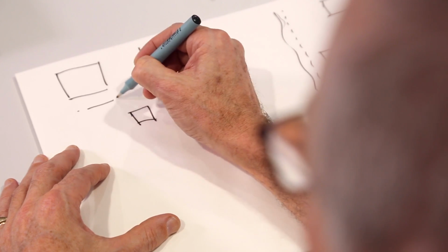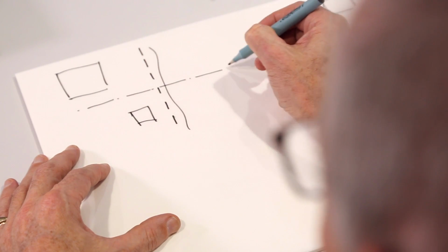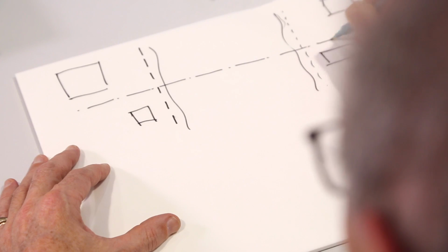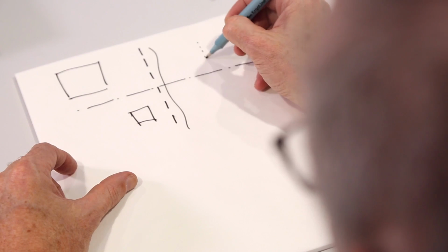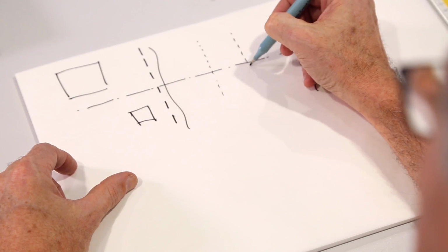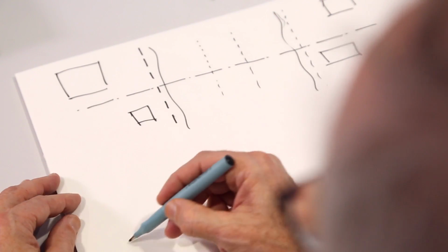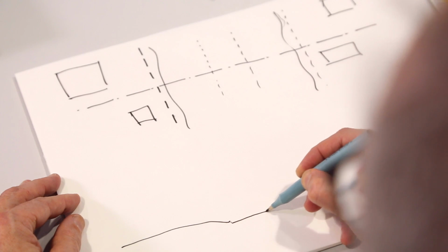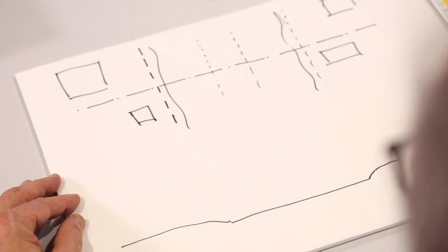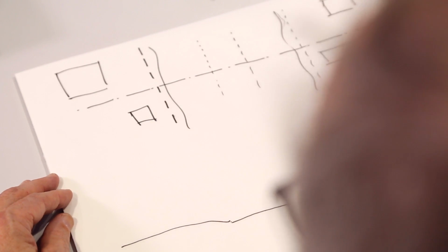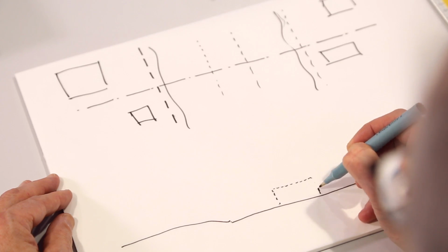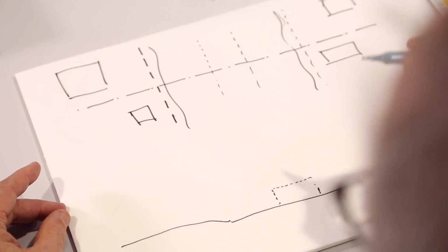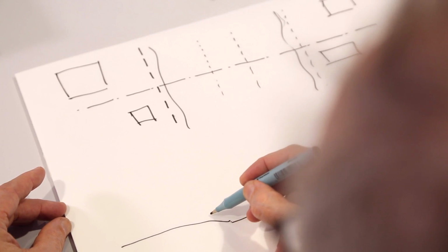And this is the position that the analysis of the site, the context, has shown us is where the bridge needs to be and the sort of bridge it is. There's a navigation channel down the middle, and very often it's all about identifying what are the constraints that are really going to be the controlling factors on the bridge alignment and so on. So let's say it's the navigation channel. Okay, that's going to have a clearance. Let's say they told us how high the ships or the boats need to be.